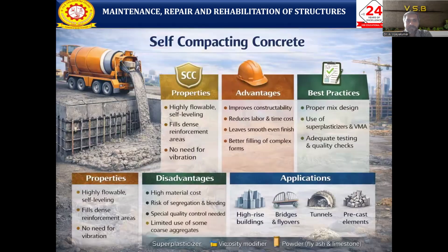properly. And about the self-compacting properties: it will be highly flowable, like water it starts to flow and automatically self-levels. It fills dense reinforcement and all areas easily, with no need to vibrate like conventional concrete. Okay, so automatically it improves constructability. Labor and time costs are also reduced, with a smooth, even finish and better filling for complex forms.